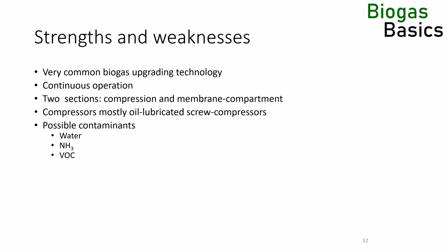Aromatic hydrocarbons like BTX are breakdown products of amino acids and can be found in the biogas of plants that have a protein-rich diet. Most AD plants do not measure VOCs on a regular basis in the biogas, but recently online VOC analyzers have been introduced that can also measure ammonia. They are recommended for waste fermentations or larger AD plants in general.